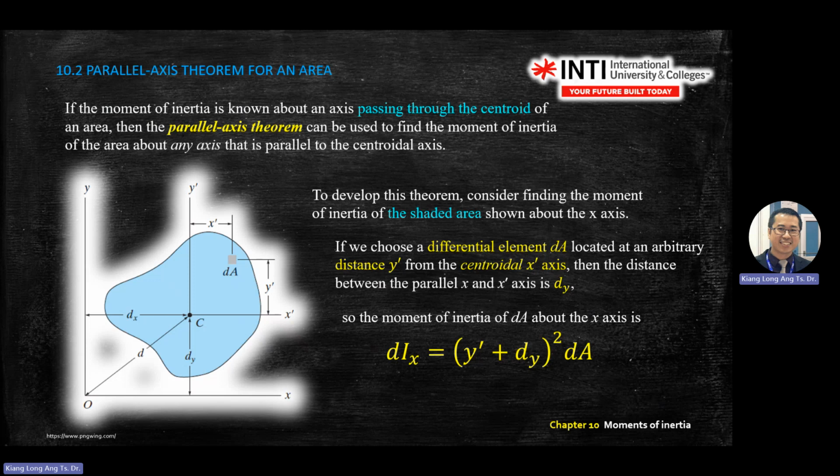But now we are more interested to find the moment of inertia with these small pieces of equation. So we want to find distance from the x-axis. Ix is from the x-axis. So here is y. To find the distance from here to here is this one plus this one. Here is dy plus y bar squared. It's the same concept like what you learned just now.